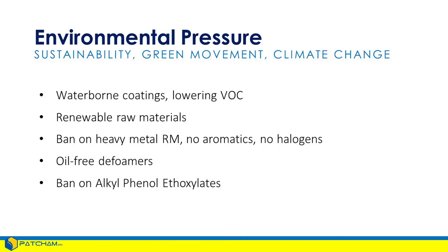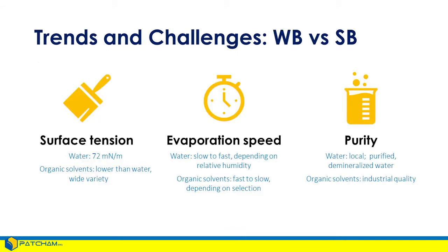Eventually, when the water's dry, these mineral oils migrate to the most hydrophobic interface, which is the air interface. And there, prior to their evaporation into the environment, they reside there as sticky, oily materials to trap dirt. So it helps the dry paint get dirty quicker. And then finally, the ban, existing or upcoming, on alkyl phenol ethoxylates. So what are the challenges, Kate, that occur when we shift from solvent-borne to waterborne?